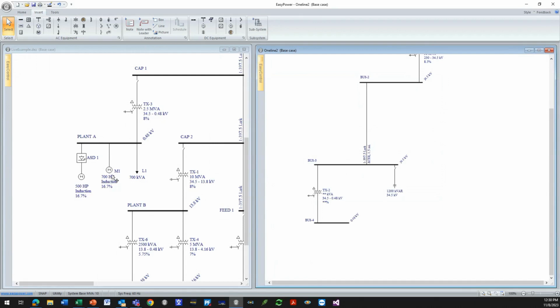And by the time this load and this motor go up through this transformer, the transformer has a significant amount of impedance. These are going to be seen as less important. But the current injections from the adjustable speed drive, the harmonics, are definitely going to flow up and accumulate onto this bus. So I want to include those.